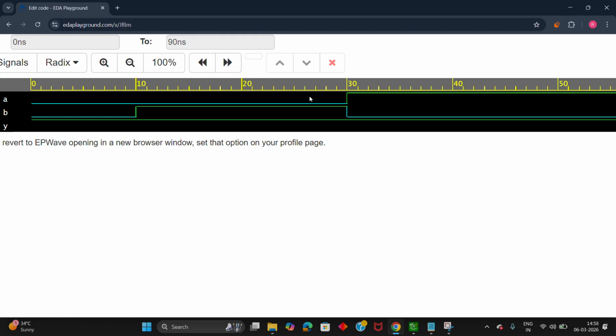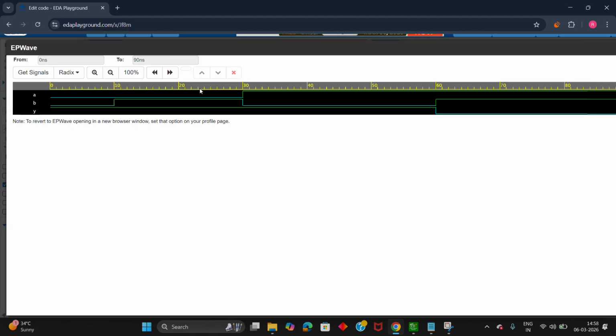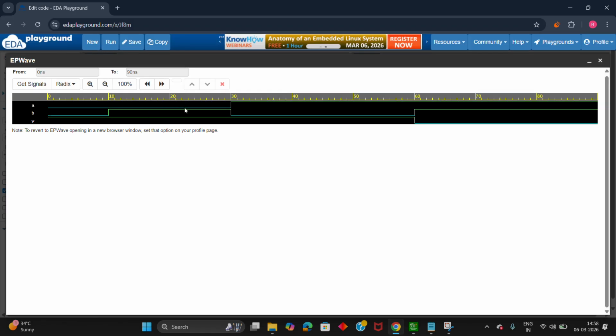Again, we are waiting 20 nanoseconds. Why only 20? We have specified it like that. The time delay which you specify in the code is your wish. So it is going to wait another 20 nanoseconds from the 10 nanoseconds point of time. From 10 nanoseconds, another 20 nanoseconds will be equal to 30 nanoseconds, not equal to 20 nanoseconds. We can get confused in this particular understanding of the waveform and the delay.